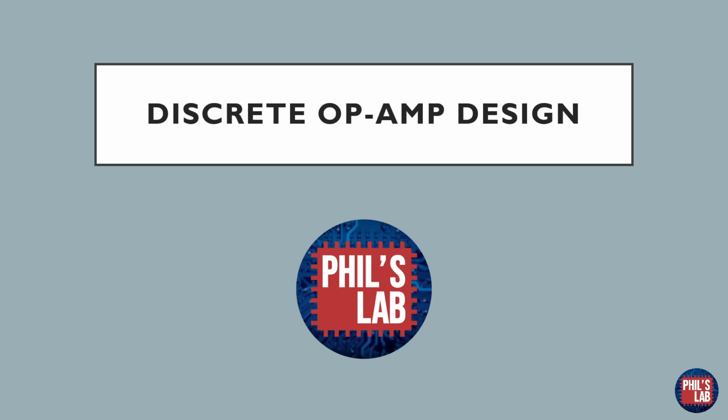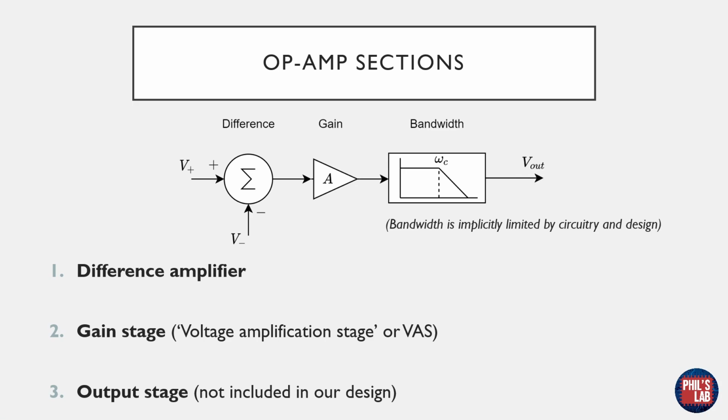Now we've covered basic op-amp theory, we can move on to a very simple discrete op-amp design. We'll go through section by section, but in essence, in most op-amps there are 3 main sections. There's the difference amplifier, which we saw before, which essentially takes V plus and subtracts V minus. This difference amplifier can also have some gain of its own. The next stage is typically a gain stage to provide further amplification and increase the open loop gain A. And I'll call that the voltage amplification stage, or VAS for short.